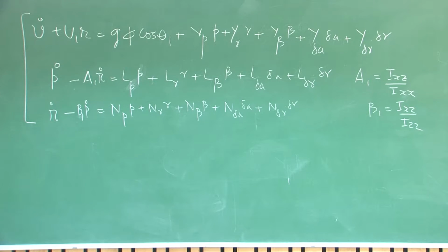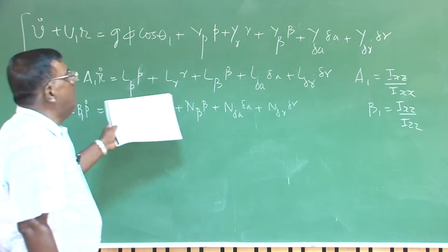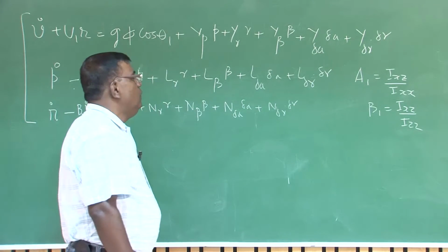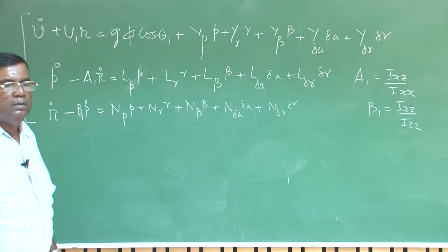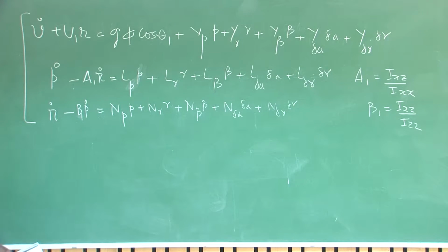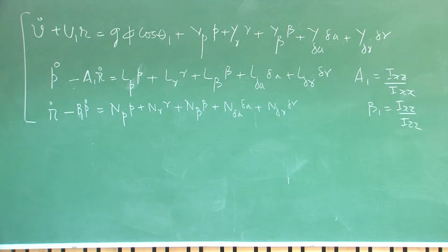Okay? And you have seen that we have made the aerodynamic model fairly simple. We have not talked about beta dot. There could be delta r dot also, but we are taking a simple case. Okay? I am sure once you know how to do this, you will be able to do the second and third equations. What is important for you to know is the expression for Lp, Lr, L beta, so that you can cross check yourself by doing it. So let me write those.